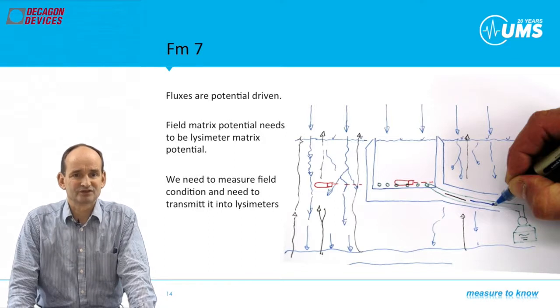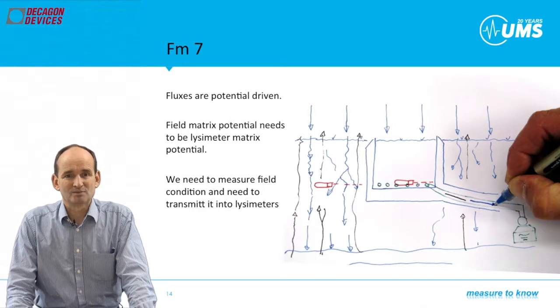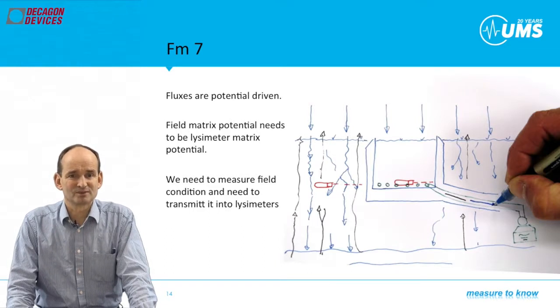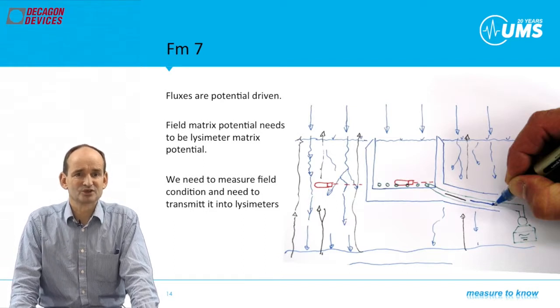We need to take off water from the lysimeter in the saturated but also in the unsaturated range. Therefore, we need suction cups or suction plates. While plates can clog due to sediment processes, it's preferable having suction cups mounted with a sedimental distance to the bottom plate. Further, suction cups work reliably over years, while plates need special care not to crack due to the heavy load or getting leaks.